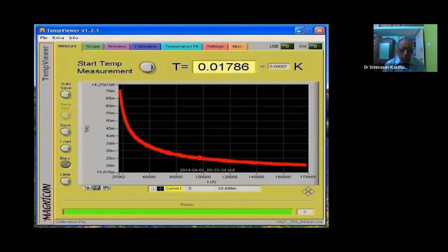So a typical noise spectrum is going to be something like this. So you can compare the noise spectrum at one particular temperature with the noise spectrum at another temperature, and thereby you will be able to get the temperature with respect to the standard one, the temperature of the new zone, you will be able to measure, right?